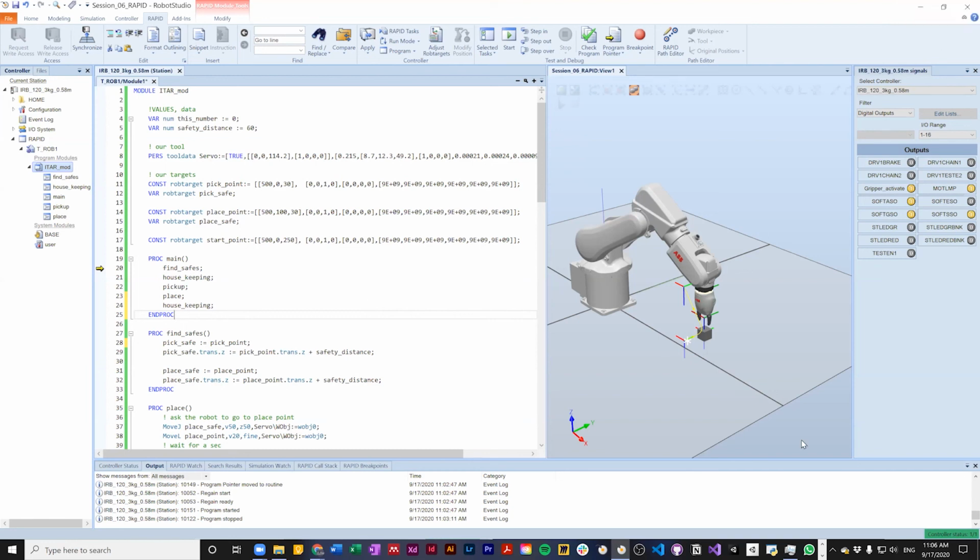I have a quick question. So when we synchronize, can we always synchronize to station? Can we always select the whole robot instead of picking where? You can always select the whole thing. The problem is that Robot Studio is going to remember all the things that you have already synced and then add these things on top of them. So for example, you may have like 10 target ones or 10 different pick points, which are just duplicated on top of each other.